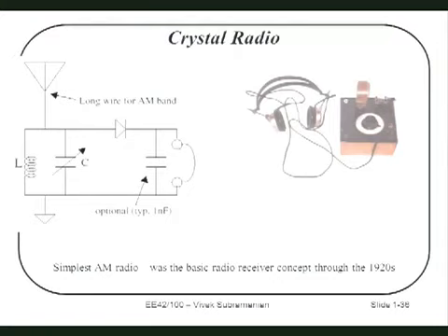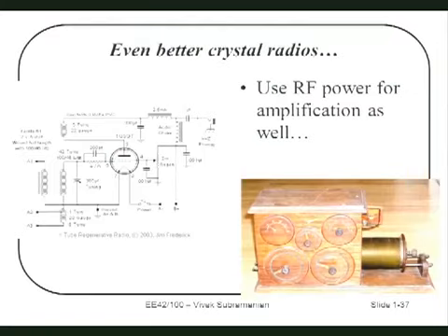You can take another step. And this is just another version on this that someone else came up with afterwards. That is called a regenerative radio, where you say, well, I'm using the RF to make a batteryless radio, but given that there's lots of radio frequency power available, I can even use that to essentially generate a power supply for local use. And that's what this circuit does. It essentially has a batteryless radio plus an amplifier, and the amplifier power comes from the radio itself. That gives slightly better sound quality. And these are kits that you can buy as well.